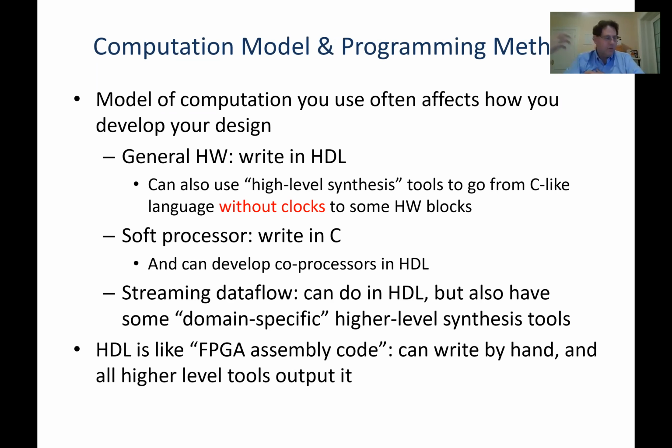You're thinking of a compute model, you're thinking of what hardware that will turn into, but it can allow you to be more efficient in doing that by taking away some of the details, like exactly what all the clocks are and some more details of the hardware. But you have to be thinking about what the hardware is going to look like, usually. I mean, I guess I can't say that always, but usually that's how you get the best results with high-level synthesis.